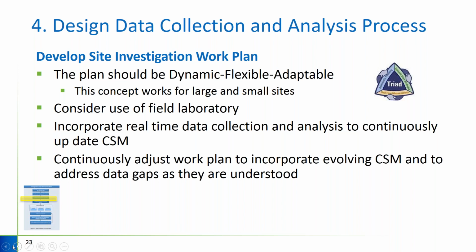It might be considered screening level data, but you're generating so much of it for a relatively small expense compared to drilling a lot of wells and collecting groundwater samples and having those results validated to the highest degree. That can get really expensive. So especially at this phase, when you're still building your conceptual site model, these screening level tools that provide real-time data can be very valuable.